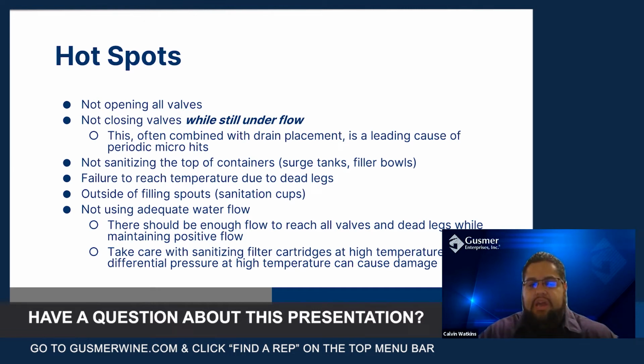And again, not using adequate water flow. So dead legs, water flow. Make sure you have enough water flow that you're able to reach all your valves and dead legs while maintaining a positive flow at the outlet.